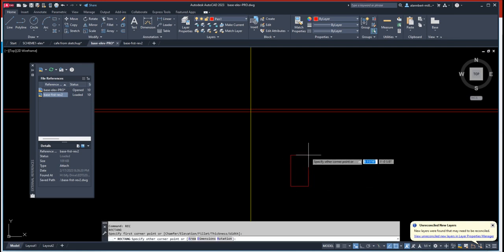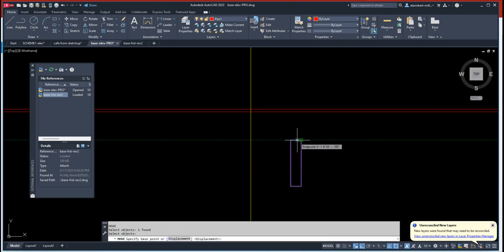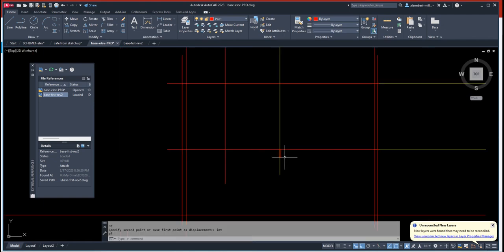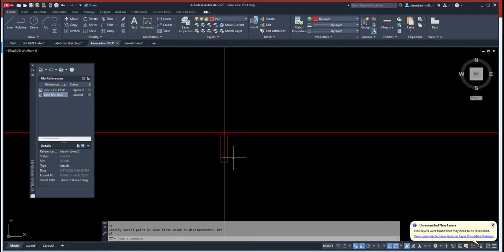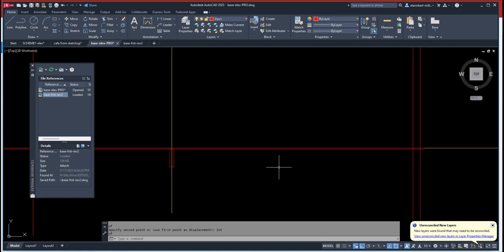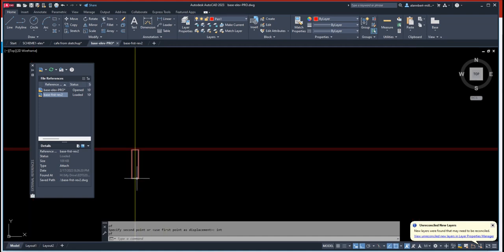So I'm going to do a rectangle. I'm going to do a 4 comma 18, enter, and then I'm going to just move that from this midpoint to this intersection here. Okay, so that's my beam, and that's 18 inches. And then you might have now here your structure goes left and right. Okay, so what kind of structure am I putting here? It's an open web truss, and you can just do a diagram of what an open web truss looks like. Okay, so normally it will be as deep as the beam. It could be shallower, but let's just try to make it as deep.